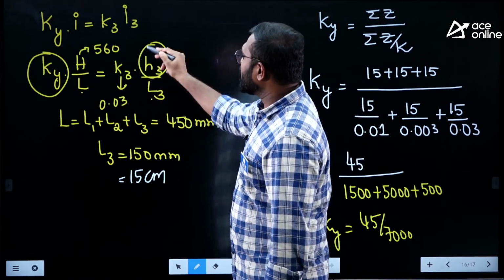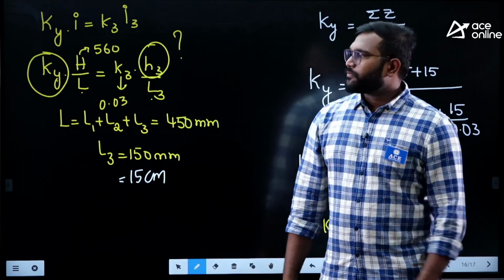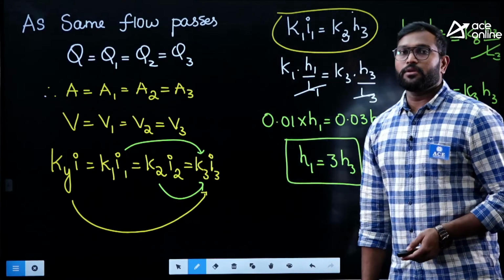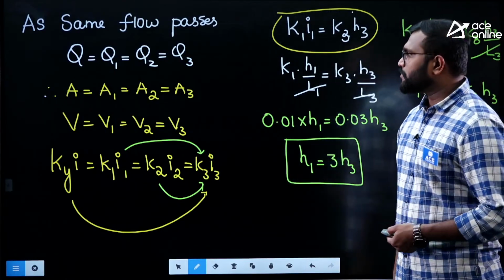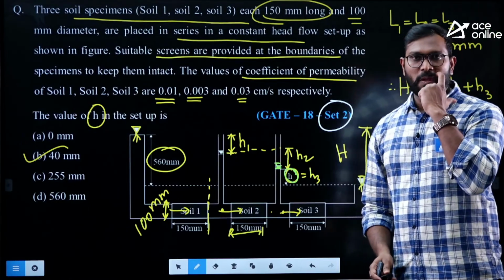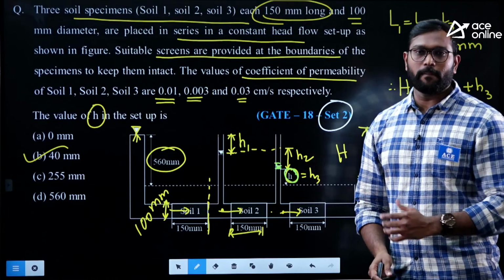You can find out the H3. This is one way, and this is one more way. So I hope you understood the two models. My whole point of view is how to apply Darcy's law and how it should be applied for the flow perpendicular to the bedding planes.